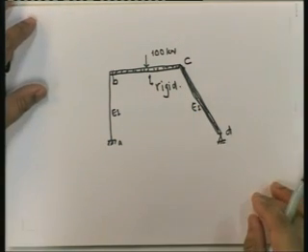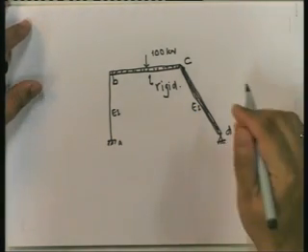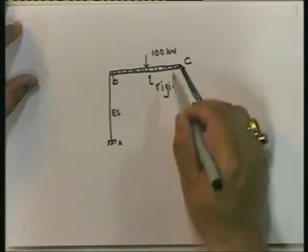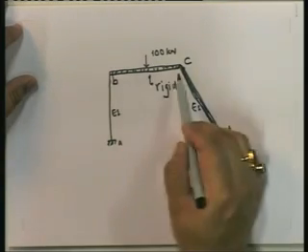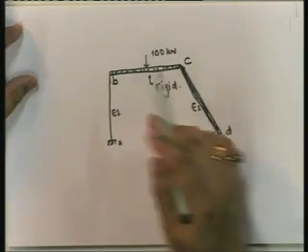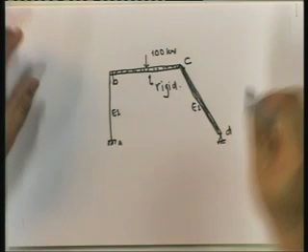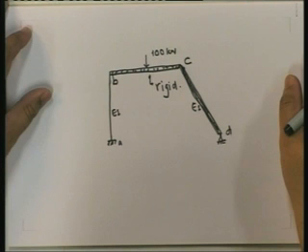Okay? So today we are going to look at this, and this is a more realistic problem where the columns are flexible and the beam, essentially because these are normally monolithic with the slabs, and therefore these are T sections, and the EI values for beams are typically much larger than those of columns.